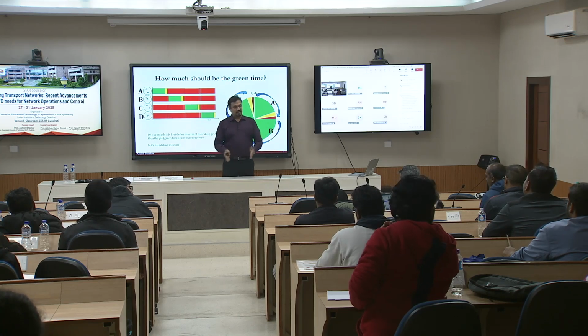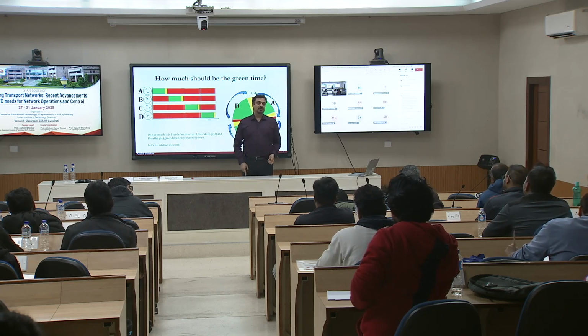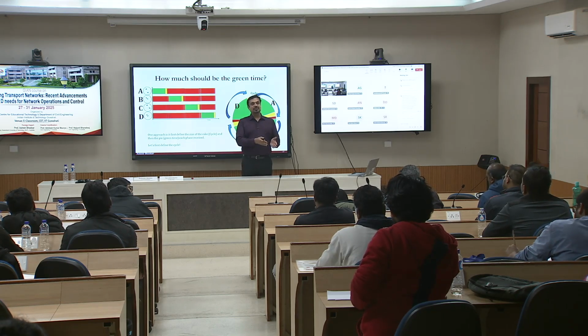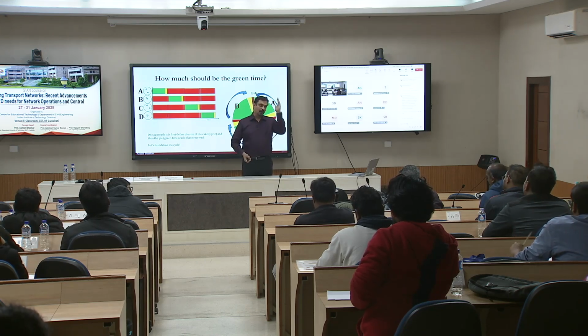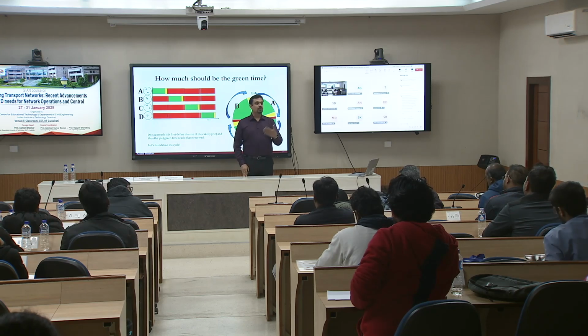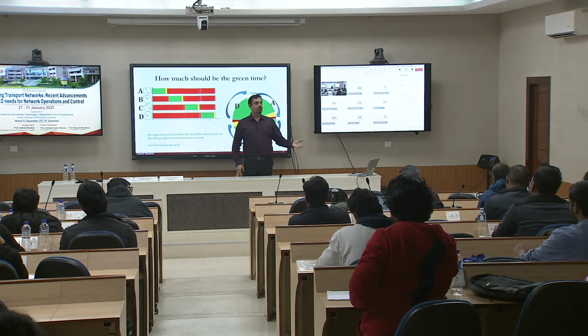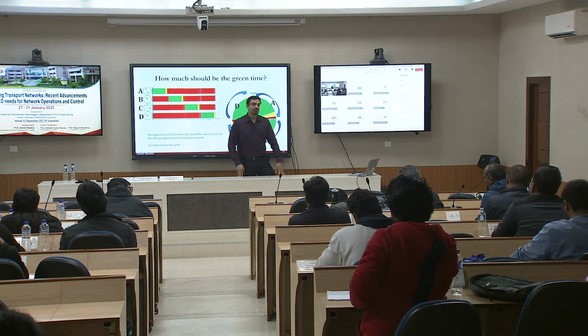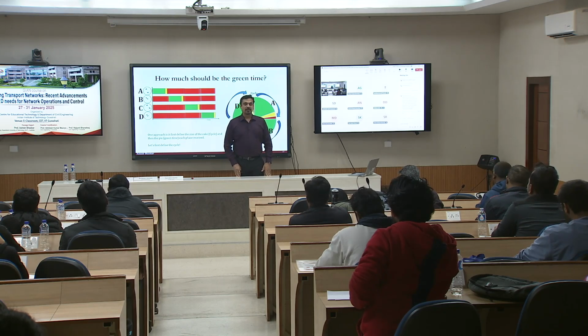Another one is you might have a slightly upstream detector, which is observing the headways, and then there's a counter. If the unused headways are quite large, cut it off. So these are certain rules that the controller might have to make the early cutoff. Those are mostly based on loops, or it can be based on other technology also, but they are considering the headway between the vehicles at that time.